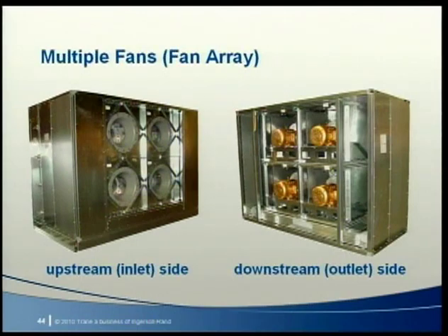Historically, most air handling units have used a single fan wheel, although the use of a few fans in parallel has been somewhat common. Over the last several years, however, the use of 4 or more fans in an array has increased in popularity. A fan array uses multiple, smaller fan wheels arranged in parallel airflow paths. Typically, direct drive plenum fans are used in the array. The example in this picture shows a 4-fan array.